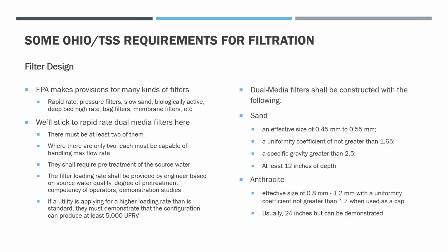The filter loading rate is going to be provided by the engineer based on source water quality, the degree of pre-treatment, and the competency of the operators. It's a very big deal, of course. And of course, demonstration studies can be used to determine what filter loading rate can be approved.